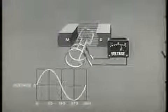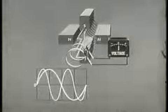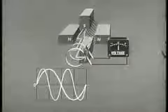In this example, the two-pole machine used has one magnetic field. As the armature makes one revolution, one magnetic field is traversed. Adding another pair of poles adds another magnetic field. Now there are two magnetic fields. The armature moves through one field in half a revolution. In one complete revolution of 360 mechanical degrees, the armature passes through two fields equal to 720 electrical degrees, and 2 cycles of AC are generated. Frequency can be changed in the AC generator by the introduction of additional magnetic fields.